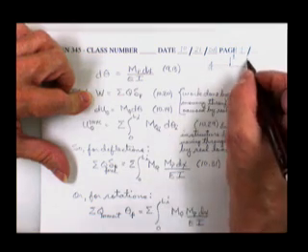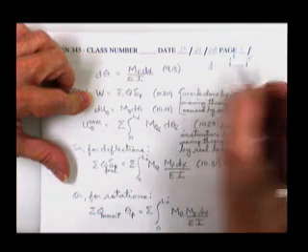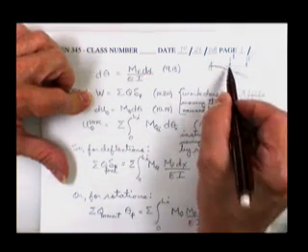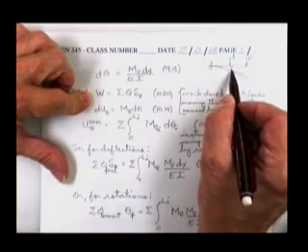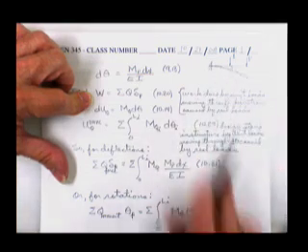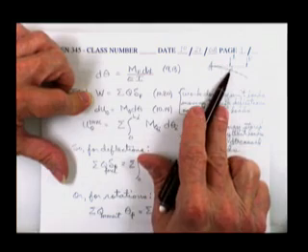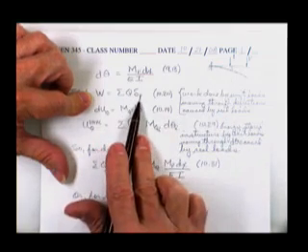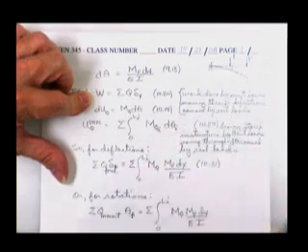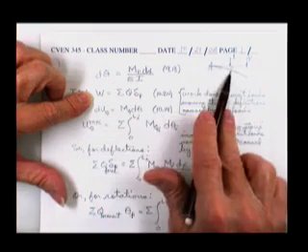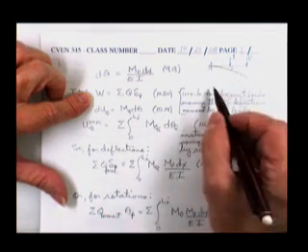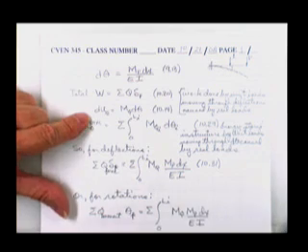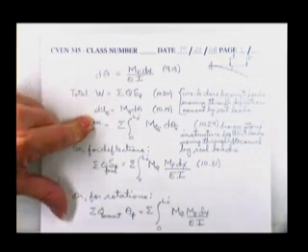And then if you put a real load on the structure, it will bend the beam some more, and that unit load travels through this deflection at this point and causes some work. And that 1 times that displacement, that work is stored in the beam due to the work done on the beam. It's strain energy if it's bent. If it's a truss, then it is deflection. If you bend something, we've already done the stuff for axial loads in bars.